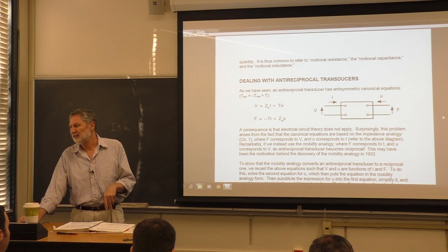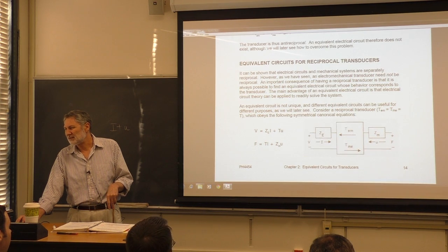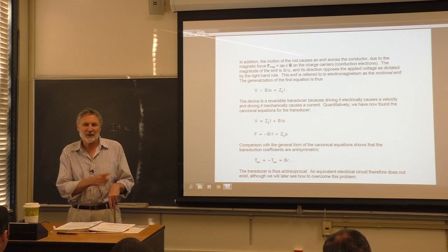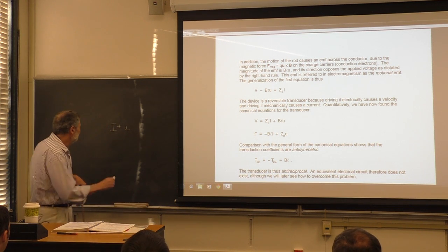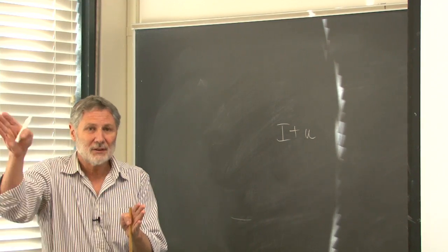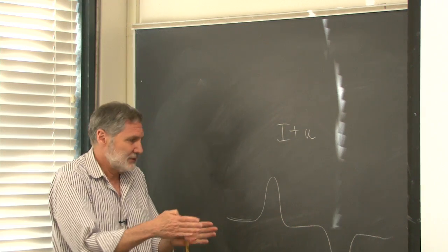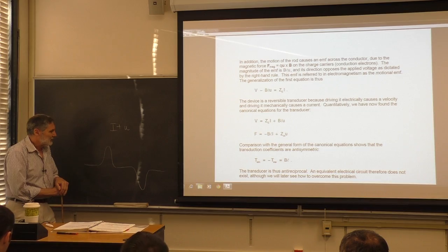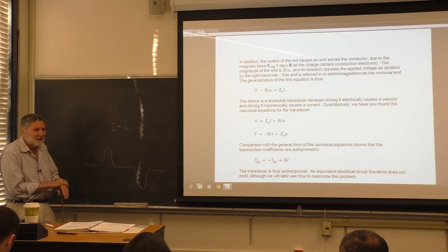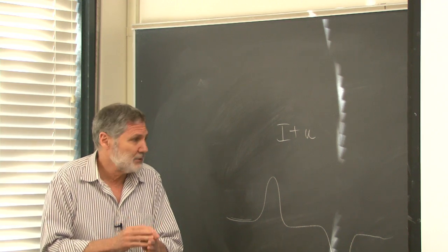Okay, so the next thing here is, you remember way back, a nice simple transducer with that great demo. I'm still excited about that signal from the wire going back and forth through the magnet. Wasn't that beautiful? It's because the magnetic field was confined to an area here, and the wire was moving with a large amplitude. We got this voltage signal that went like this. When the wire is outside the magnetic field, nothing's really going on. Then as it decays and the amplitude becomes smaller and smaller, eventually it's within the magnetic field. As it gets smaller, the magnetic field gets more and more uniform because the displacement's smaller. It goes to a sinusoid.